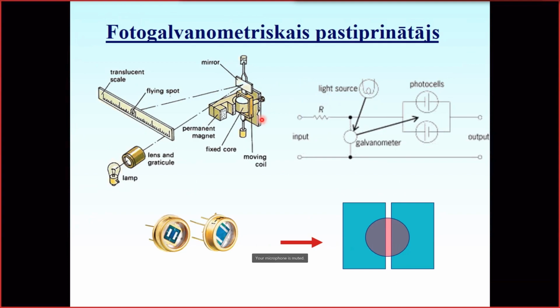I wouldn't say that galvanometric amplifiers are still in use, but they sometimes may be, because they provide very high sensitivity and are quite robust to noise. Maybe they are even superior to any type of electronic amplifier, especially for very low signals, and they work very well with pulses in the form of so-called ballistic amplifiers.